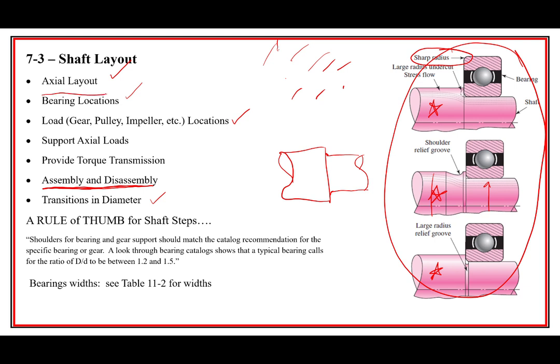We've kind of made an assumption that we know what the axial layout is. It might be the case in the real world where we find that we're stuck and we can't build a sensible shaft. A lot of that has to do with somebody making the thing too long, right? Having a long shaft means you're going to have large bending loads. Maybe it's better to go back and revisit the axial location of stuff. The main thing that you're doing is transmitting power, and where those things are located might be something that you want to revisit.